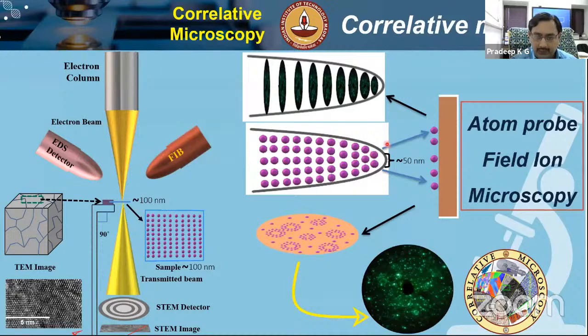In principle, even when the atom probe runs at ultra high vacuum, hydrogen is very difficult to eliminate. So even in a natural measurement on realistic samples, we see traces of hydrogen being detected, but we will not be able to say whether this is from the material or from the ultra high vacuum chamber. But if we selectively add deuterium in defined proportions into the sample, and that deuterium can be well identified, and since we already know how much we might have charged, we can look into the quantified data for whether this equivalent amount of deuterium is available.